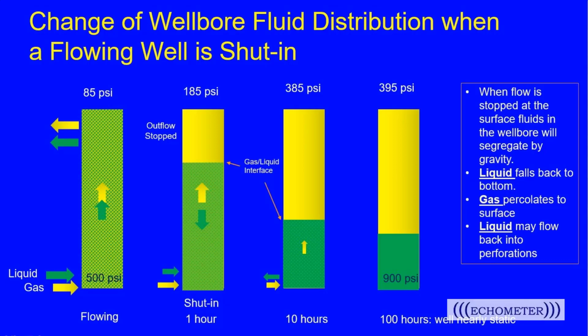And if fluid is pushed back into the perforations, the first fluid that's pushed back will be the water. If we're not producing above critical velocity, if the well's liquid loaded or there's a liquid level in the tubing while we're producing, then we probably have a natural separation already of our oil and water in the tubing.